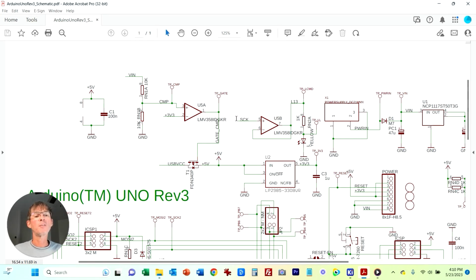What it does is basically whatever's on this positive terminal ends up on this output terminal. Then you're thinking, okay, what's the purpose of that? But the difference is, even though the output voltage will track the input voltage, the buffer allows it to provide more current.